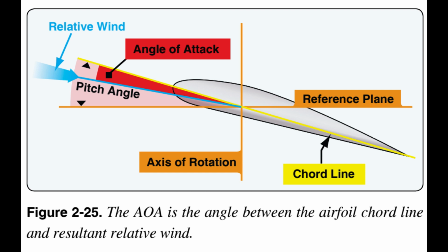Several factors may change the rotor blade AOA. The pilot has little direct control over AOA except indirectly through the flight control input. Collective and cyclic feathering help to make these changes. Feathering is the rotation of the blade about its longitudinal axis by collective/cyclic inputs causing changes in blade pitch angle. Collective feathering changes angle of incidence equally and in the same direction on all rotor blades simultaneously. This action changes AOA, which changes coefficient of lift, CL, and affects overall lift of the rotor disc.